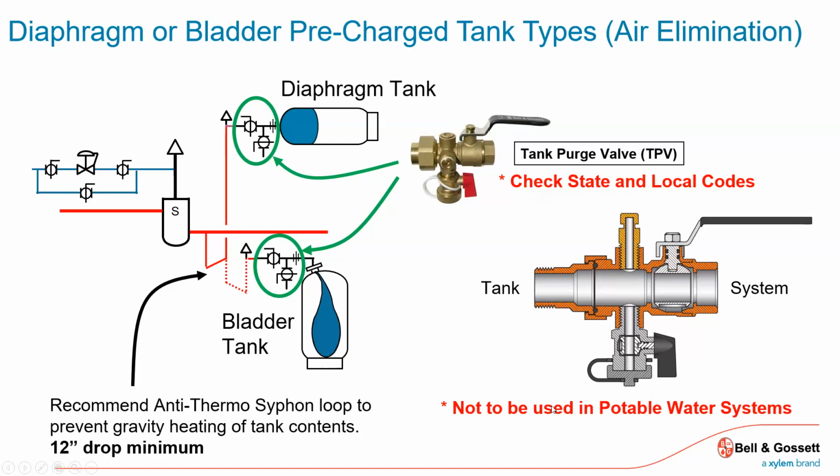So these little multi-purpose valves that the mechanicals use all the time are a nice way of being able to install the tank either way, and then be able to service it. And then if need be, with the union, we're able to replace the tank without affecting anything else within the system, because I can isolate the system from that tank. So it's a real convenient device. Instead of just sticking the pipe in, because technically that's all it needs to operate. But when you think about how do I service it, how do I check it, how do I remove it, give yourself some of this serviceability.